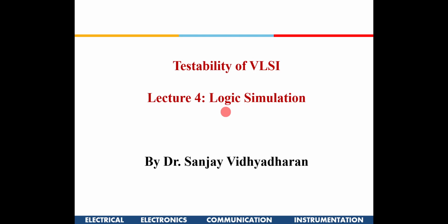And then in the next class we said that if you try to find a test vector to identify all the faults in the circuit, it will be an enormous task. So to make the testing more compact, many faults can be collapsed. That means with a single test vector, multiple faults can be detected, right?